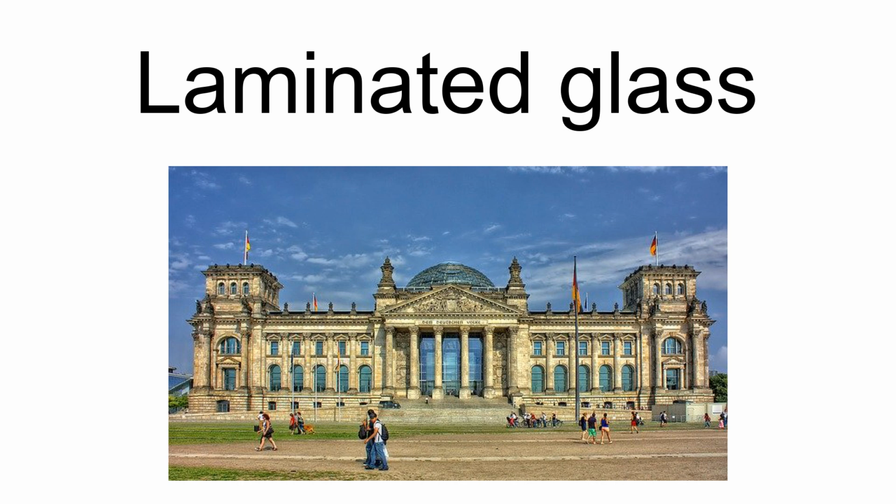Tempered laminated glass is designed to shatter into small pieces, preventing possible injury. When both pieces of glass are broken, it produces a wet blanket effect and it will fall out of its opening. Heat-strengthened laminated glass is stronger than annealed, but not as strong as tempered. It is often used where security is a concern.